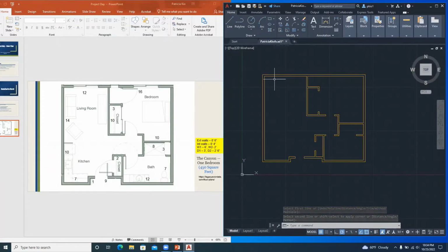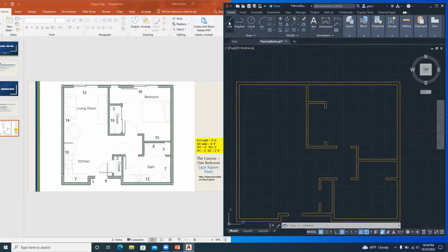What's next is the window. I want to do the windows. I'll say the window is 6 feet wide for the big ones, and the smaller window here is 2. So all we do is come to the middle of this room and draw a line, and then offset 3 feet either way. And then we'll trim this, but before we trim it, I want to mirror this window opening so that it's equal. So those are the things you consider in design, always to make the proportion look planned.